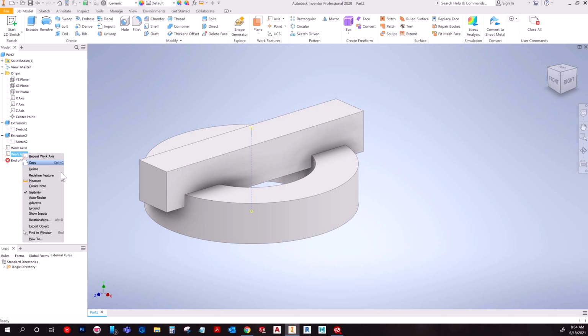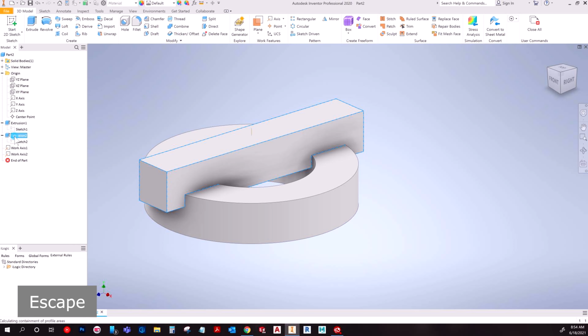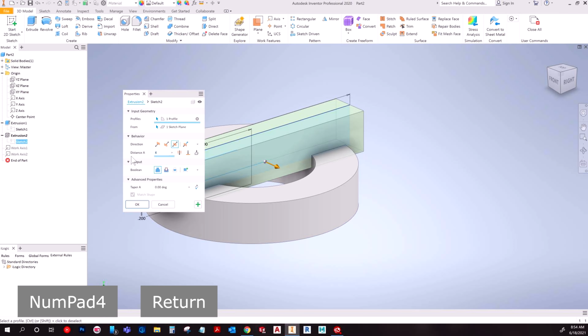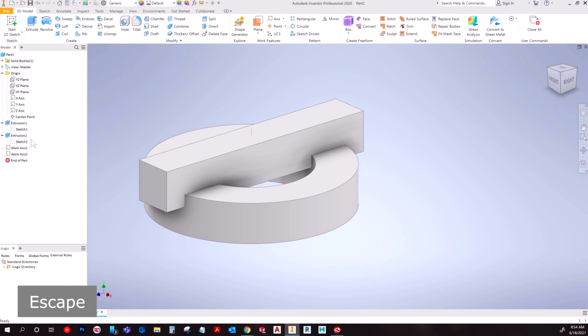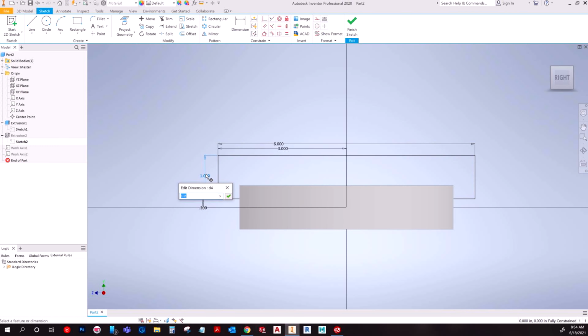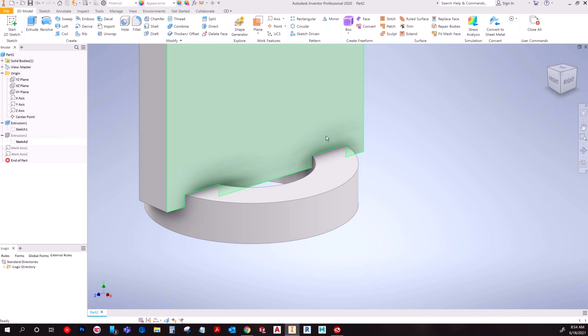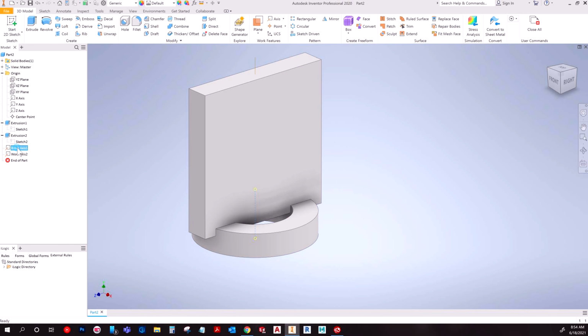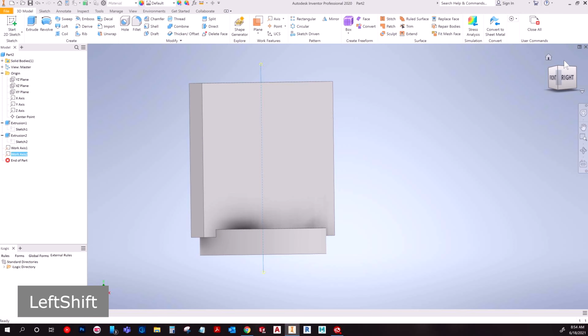Then also, you may want to resize them. What I usually do on planes and also axes, really anything, is right click them and make sure that auto resize is checked. The reason being, if I were to decide to extrude this up really tall, and adjust something like this, look at work axis 1: it's still the original height from what we had earlier, whereas work axis 2 stays proportionally growing to the actual part shape.